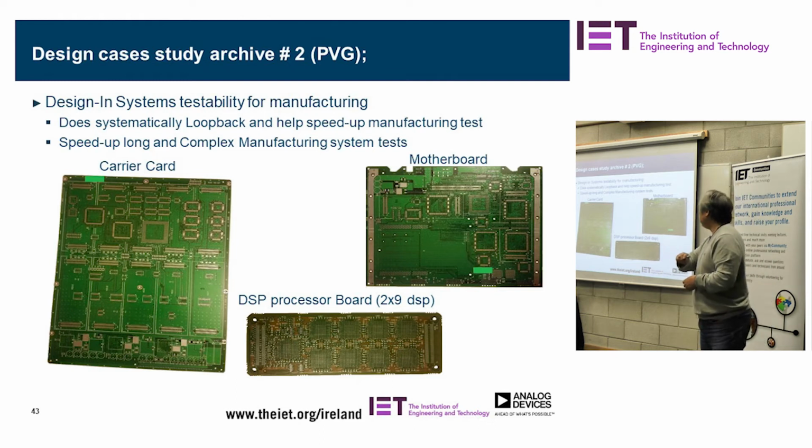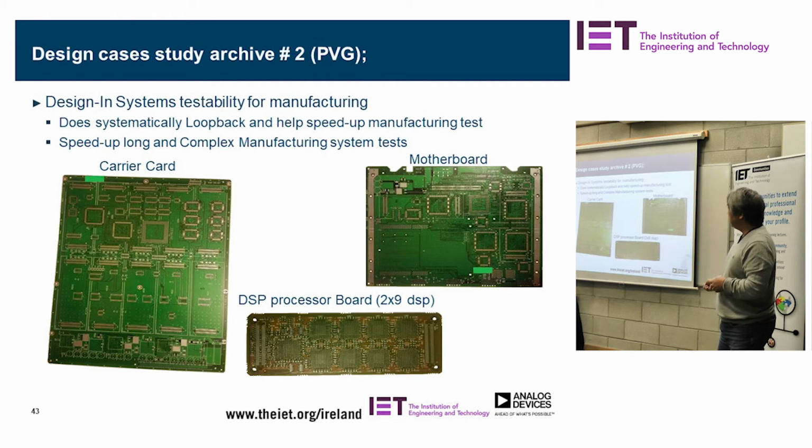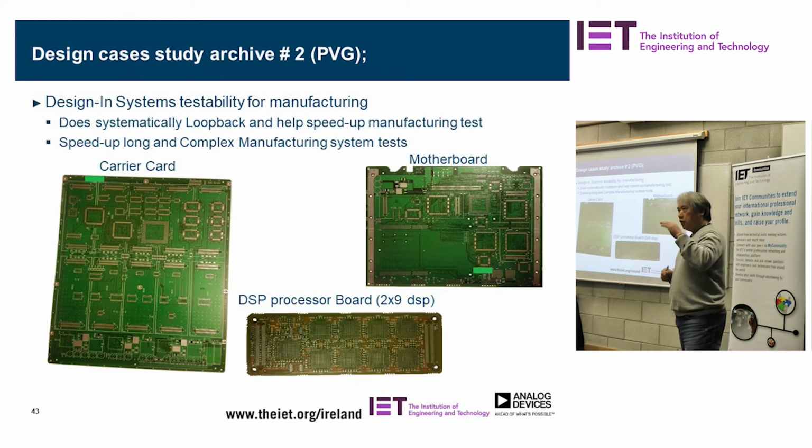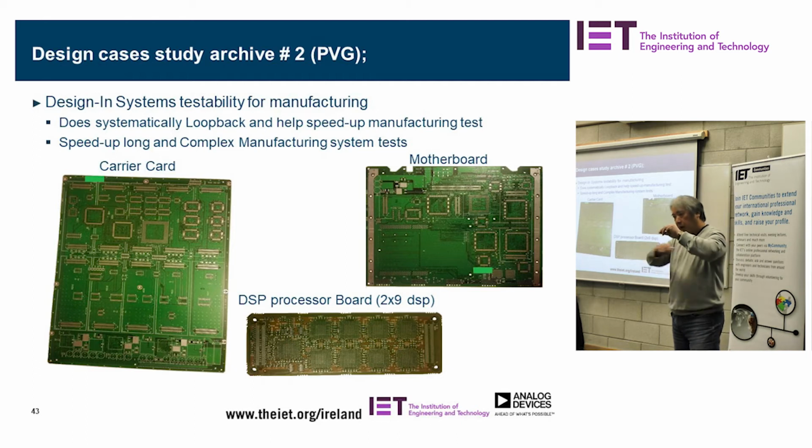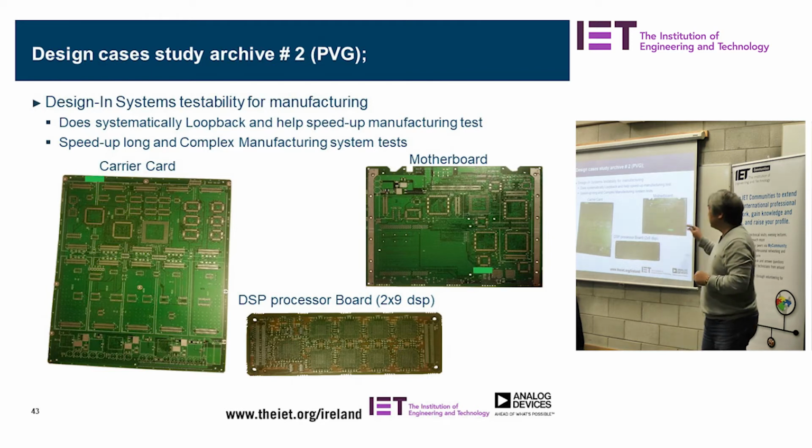Actually, even by today's standard, this is very good. This board uses sequential lamination. What they mean is that the wires do not go through every layer. You go to a layer that you specify, and then it laminates and seals off, so it doesn't go all the way down. It only goes on a per-layer basis, so it becomes very expensive. Not many people do it nowadays, and not many people are even aware of it. This can be done.